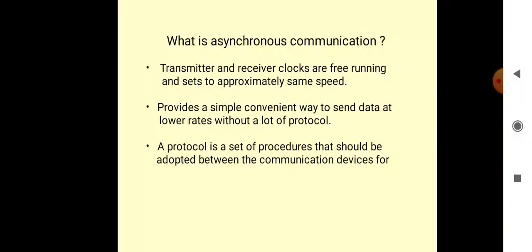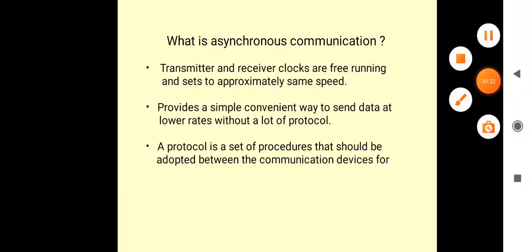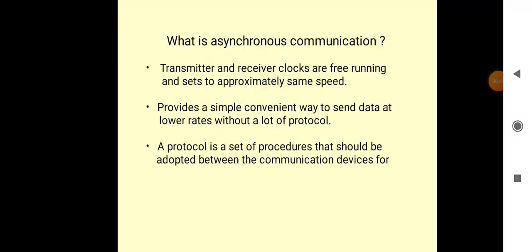So, data transmission. In digital communication systems, the signals are transmitted by first converting analog signals into digital signals and then modulated. These modulated signals are digital rather than analog signals. It means that transmitted signals from the digital transmitter are discrete signals rather than continuously varying signals. These discrete signals are zeros and ones, which might be interchanging their levels, that is either 0 or 1 and vice versa, due to the presence of noise in the channel.